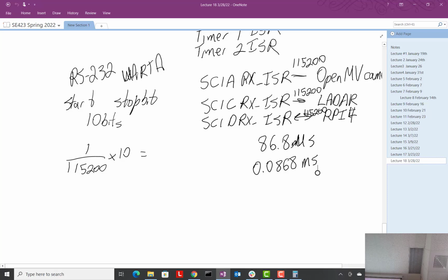And you look at 64 LiDAR distances to try to decide if there's an obstacle in front of you. That just increased your code maybe another 15 microseconds. And then you start breaking more things, right? These interrupts. So the whole point of the software interrupt, if you get nothing else out of this lecture, is that this is a safe place to do longer code. Not insanely long code, but longer code.